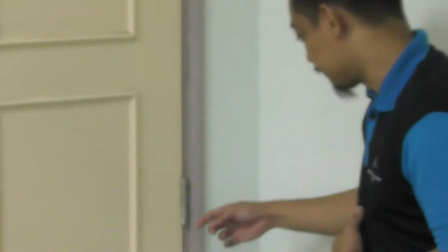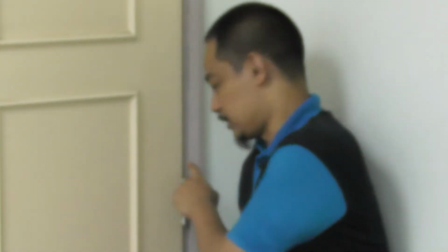So the door itself, you know how it works, right? If I assume this is my x-axis, y-axis and z-axis, right? X, Y, Z. So this hinge actually prevents any movement. This door cannot be moved that way, this way, or upwards. So when you draw the free body diagram, if this is point E, you'll have AX, AY, AZ. Hopefully you understand that.